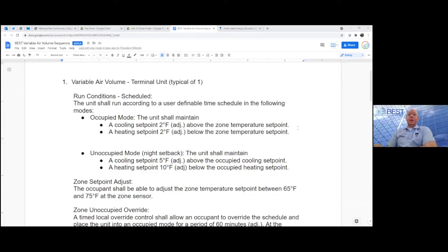But yeah, there are a number of different considerations. The velocity profile across the sensor, flow area adjustment due to dampers and coils. Every VAV box has a certain set of characteristics. And as soon as you change manufacturers, as soon as you change the BTU output on your reheat coil or change the style of reheat coil, hot water to steam to electric reheats, those will all change the flow characteristics within a box, let alone changing the input diameter of your ductwork or the input static pressure.